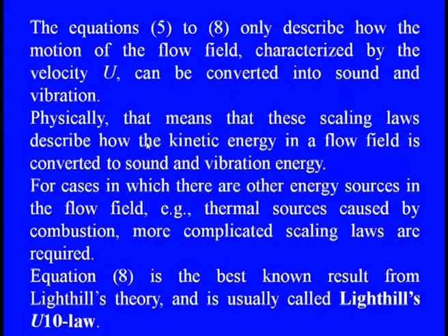So the equations which we just showed describe how the motions are there in the fluid flow and how we can characterize the fluid flow motion with the flow velocity u, which can be converted into vibrations. In the physical sense, the scaling law clearly describes how the kinetic energy in the fluid flow is converted into excitation energy, or how this energy is used for creating the excitation features in the system in the monopole, quadrupole and dipoles.